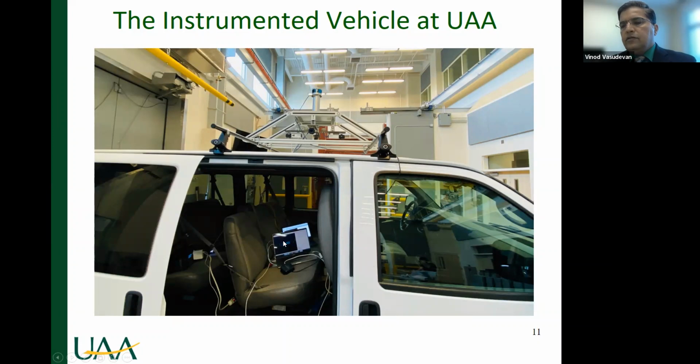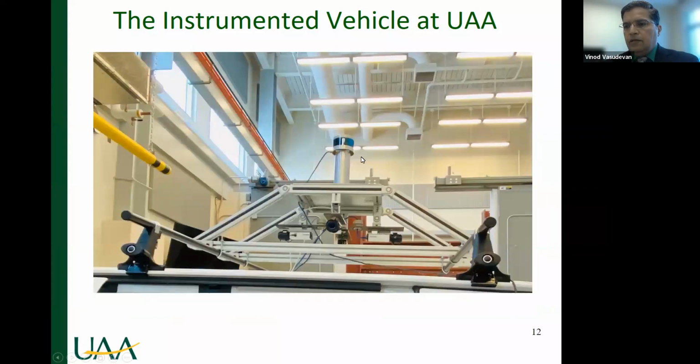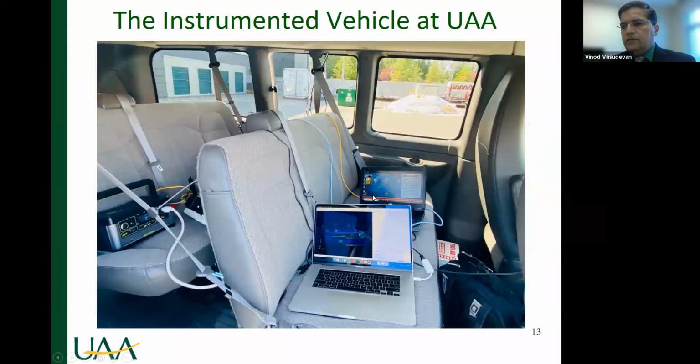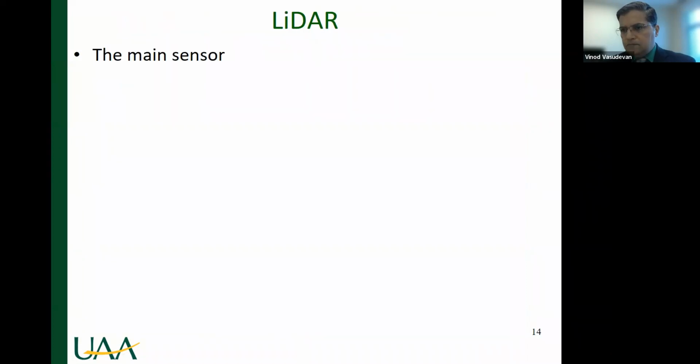Then you need some kind of a data acquisition system, because LiDAR doesn't have an internal memory, so the data has to be captured in a computer. This is the LiDAR, the camera, and these are two computers which are powered, and we have a router, etc., to collect data. This captures LiDAR data, and this captures the video data. Again, there can be different arrangements, but this is a simple arrangement, and it wouldn't cost a lot of money.